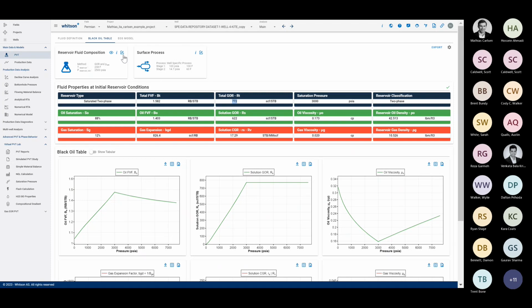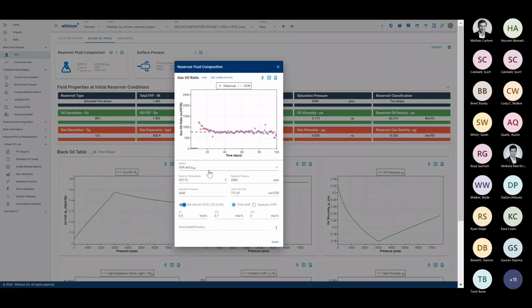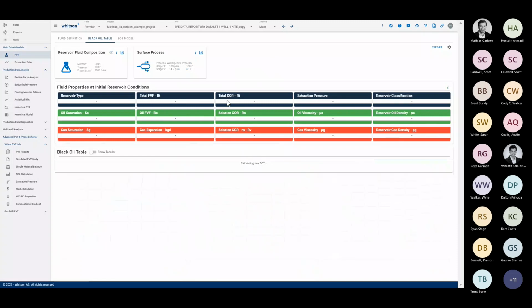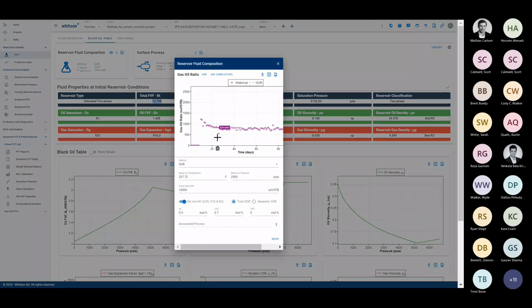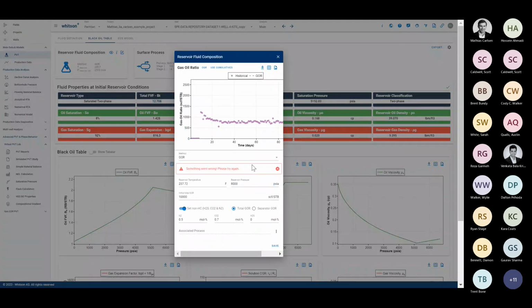And if this was a gas condensate well, I'll just show how that looks. For a gas condensate, you'll still use the total GOR value, and the total GOR will just be that BGD term divided by the little rs. And that will give you this formation volume factor of 12.7. That's just, this is a gas condensate. There's a low, let's make this 8,000 just for example. This is just to show you guys.